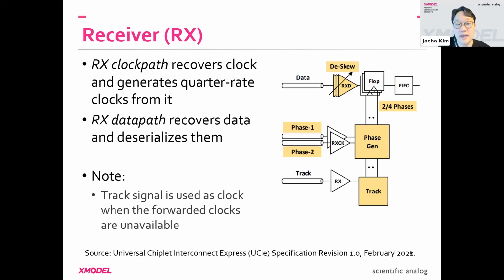That's the only way of doing it. The problem with that is because of the difference of the two simulators, the simulation is not that fast, which actually serves as a strong motivation for us to move all the analog part into SystemVerilog so that you can run both analog and digital simulation in one platform. That's the way we go.